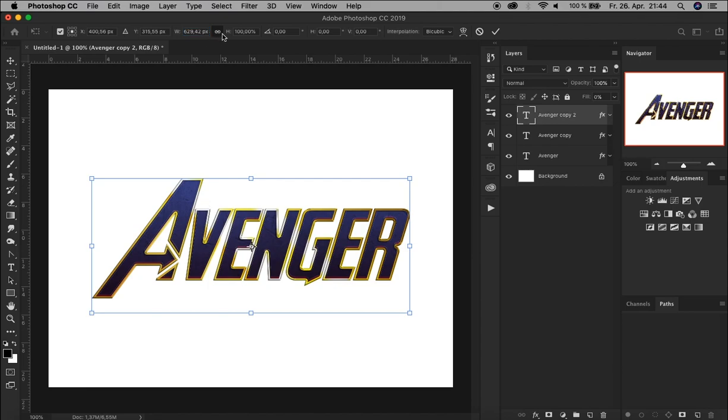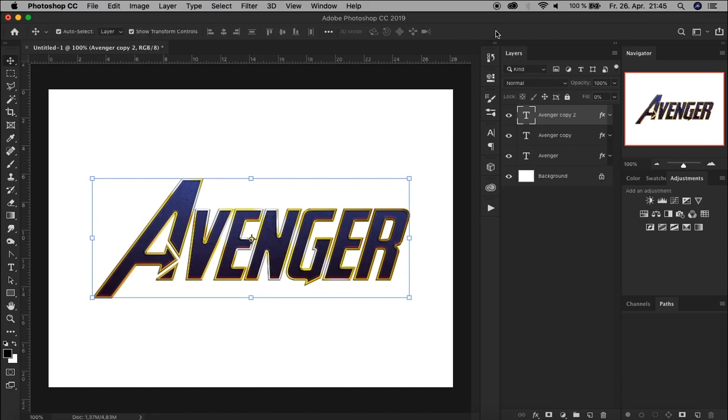First, we uncheck the maintain aspect ratio, so that the transformation we create now is only for the width. So let's click here and write minus 0.5, right? And let's confirm. The software has now changed that transformation. And because of that, we can use this transformation again and again, and at the same time, we can duplicate the layer. Now we create our extrusion by holding Shift, Alt, and Command, and then press T.